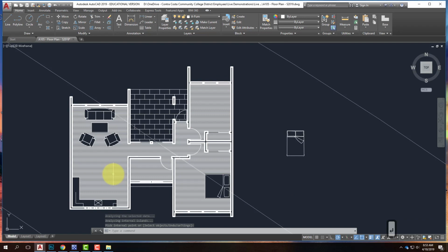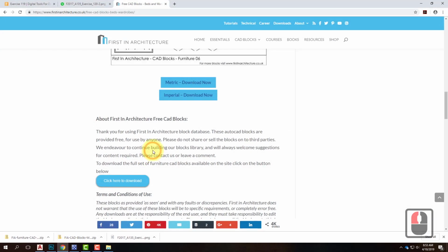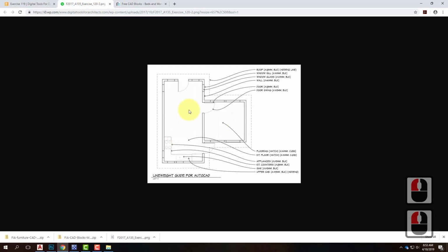Now, this would end up being really dark when it printed, so I also recommend changing the color of this hatch. It's very difficult for you guys to see on the projector here, but there's actually a hatch in here where you can see the floor, and I tell you that, let me see where it is, flooring, hatch, 0.00, and the C251 is referring to a color of 251.